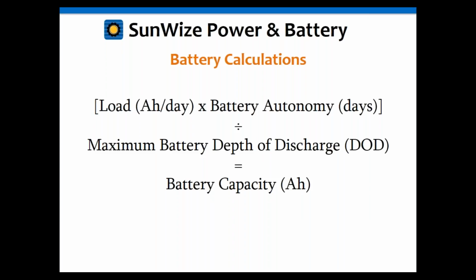If you discharge your battery 100%, two things are going to happen, basically. One is you're going to shorten the battery life dramatically. As a matter of fact, it may not even come back. It's like leaving the headlights on in your car overnight. The battery will most likely be dead and not come back. You're kind of doing the same thing with discharging a battery completely here.